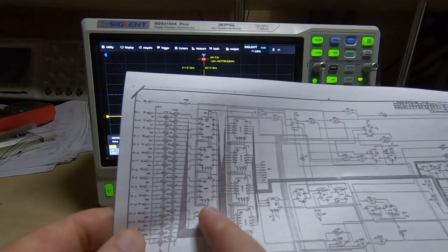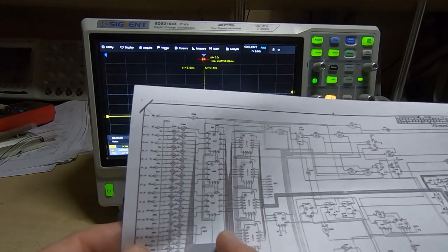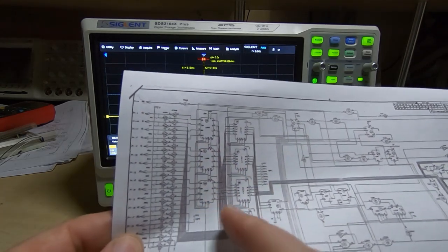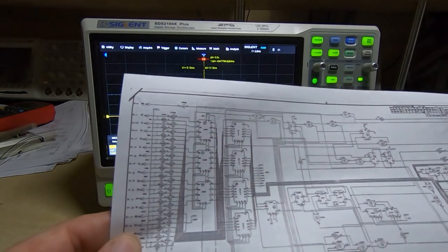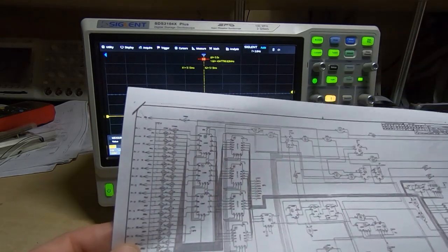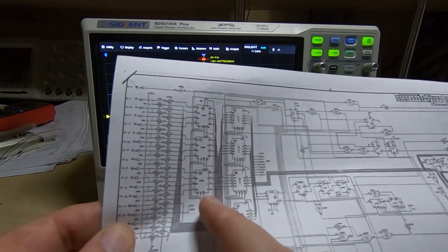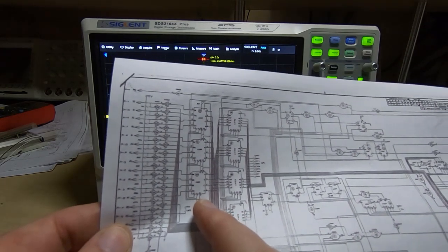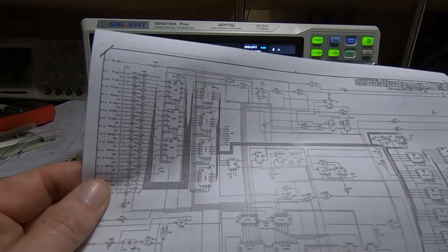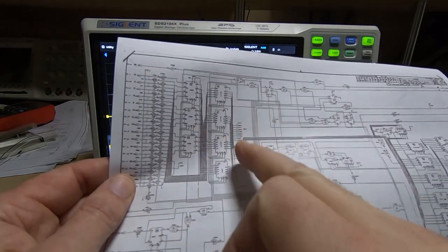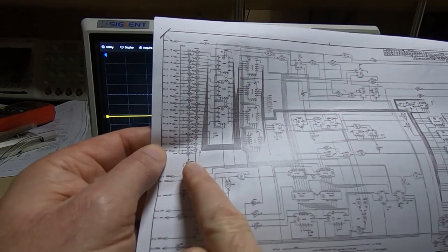But what I want to do now is look at the load. These are loadable counters, and I think what's happening is these are being loaded when they shouldn't be, and that's what's causing this kind of block effect on the screen. I think it's just rereading the same part. We can test that by looking at the load pin and seeing if the interval of the signal on there matches what we're seeing on the screen. We know that it's a 60 Hz refresh on the screen, so we should be able to work out what we're seeing and if it makes sense with relation to these signals we're seeing on here.